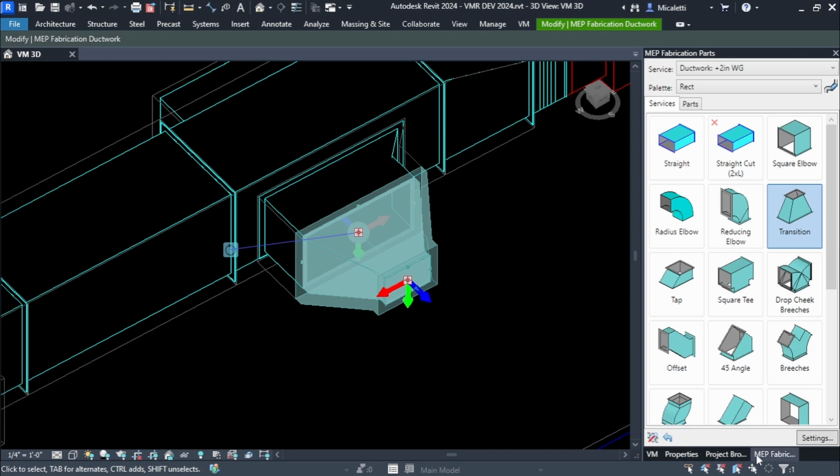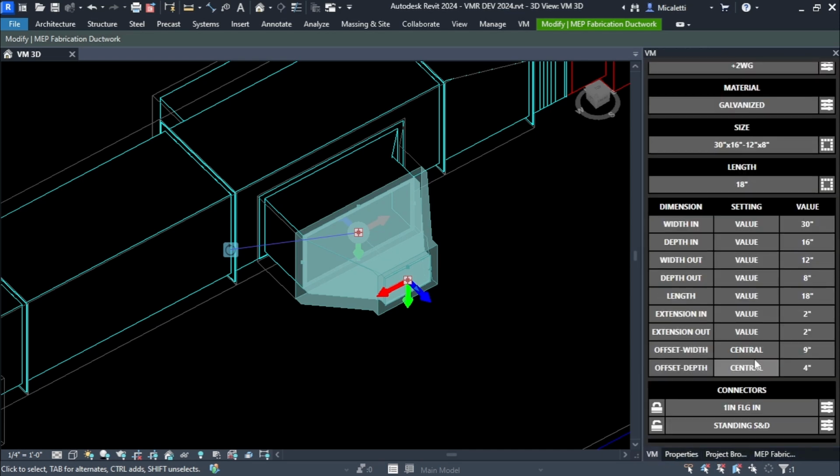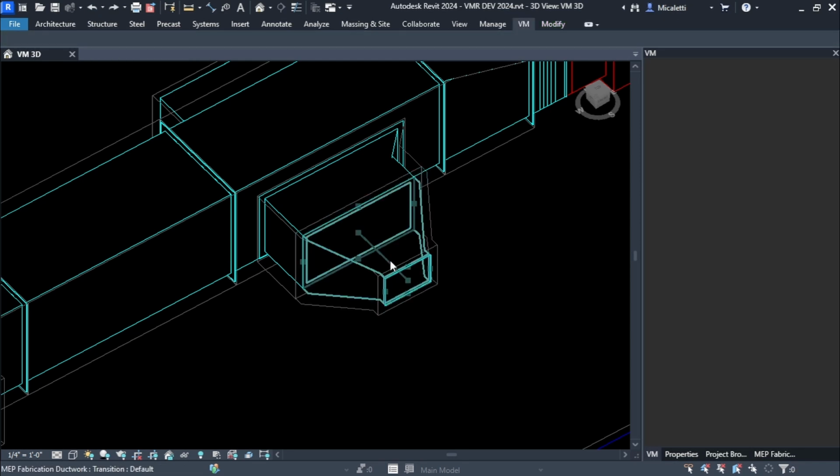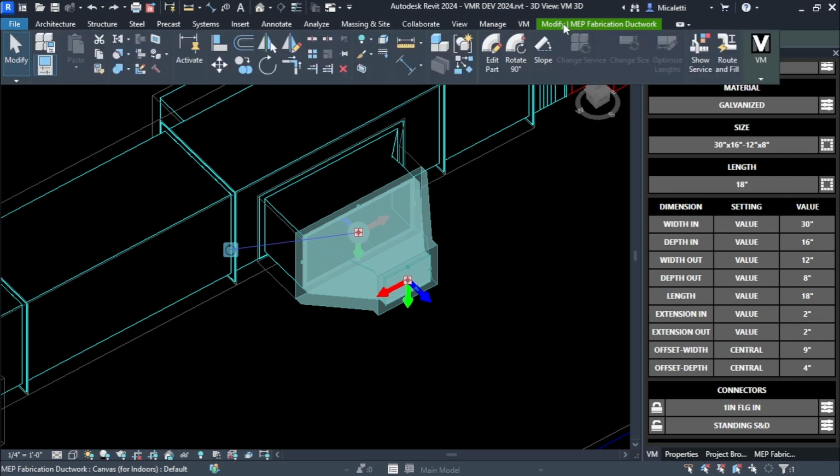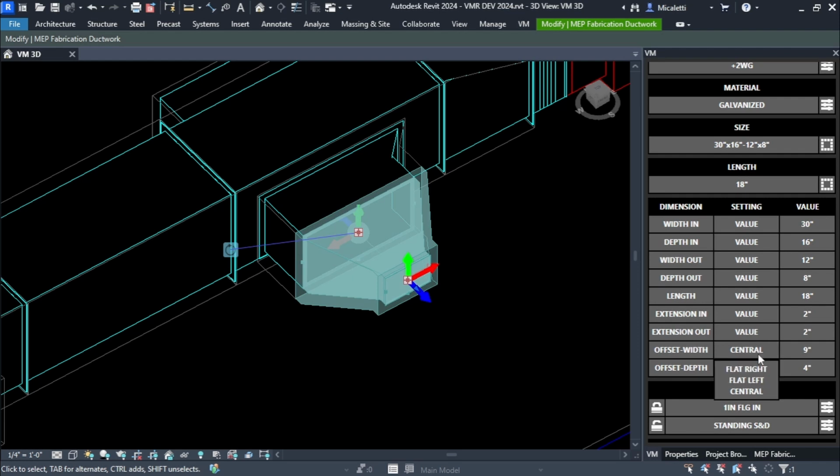It's not intuitive, because when I come in here and I say top flat, or flat top, it's going to give me flat bottom, right? Because of this problem with the attacher arrow. So this makes us aware of that. It's inherited this idea of which way is up from this tap, which is wrong. So I put this on there. I'm aware of it now. I can come up here and get that arrow pointing up, and now top flat is going to be top flat, right? Right flat will be right flat, and any offset tags that I place on this fitting will also make sense, right?